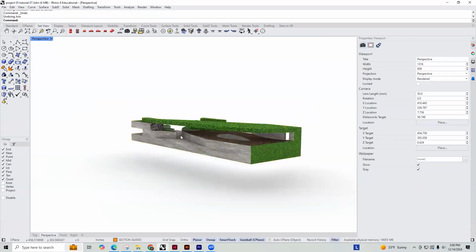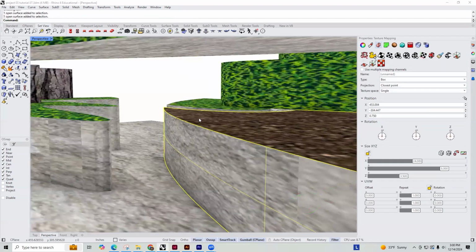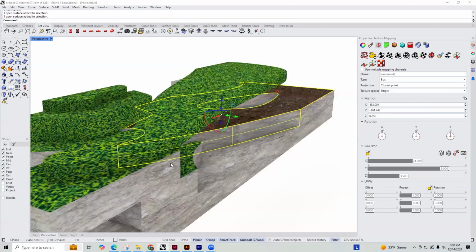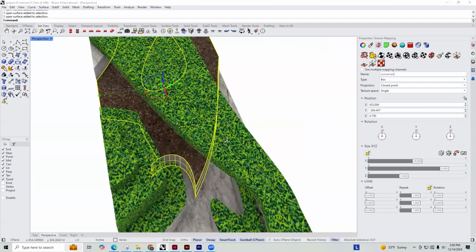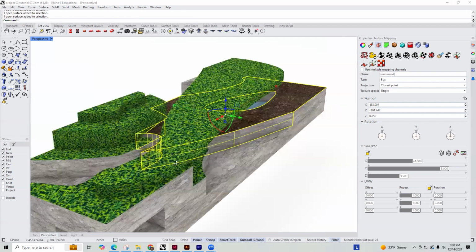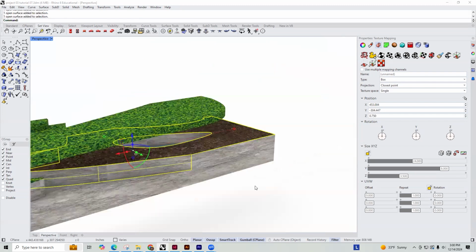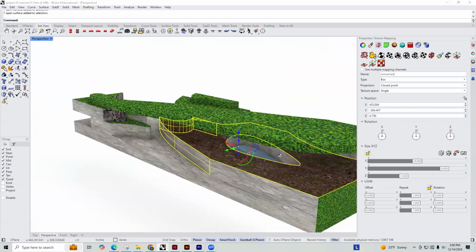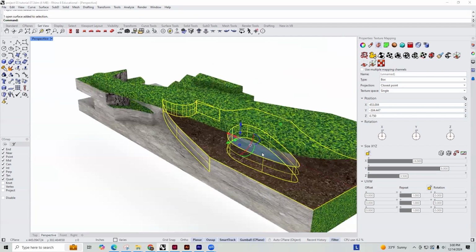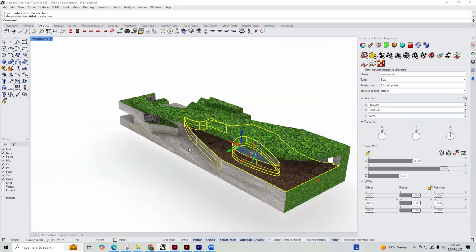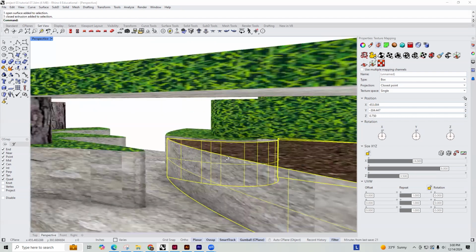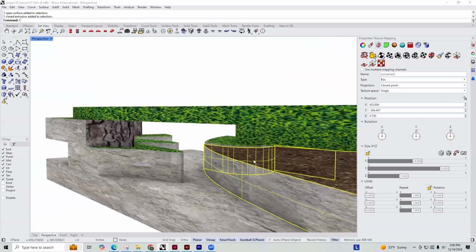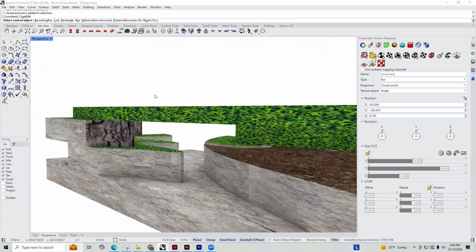All right, so that does not work. So let me just select both of these at once. I'll just select this object as if it's one piece. And what I'm going to do is a little trick to manipulate a surface. I cannot guarantee that it's going to come out very nicely, but we're going to try our best. And I'm going to cage edit this so that I can make this more walkable. So cage edit allows us to manipulate poly surfaces and turn them into meshes.